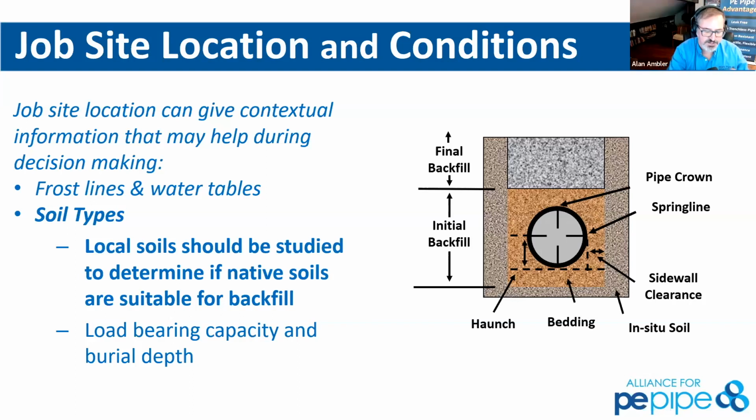That's a great question, and it brings us to one of the things that's plagued the HDD industry for smaller diameter quite a bit, which is called a cross bore. So a lot of times you can bore through a gravity sewer pipeline or a storm sewer pipeline, and then put your new smaller conduit through that pipeline, at that same elevation level at which we're having that conflict. Unfortunately, there's not really a rule of thumb that I'm aware of, Pete. The underground world out there can be pretty fierce when they're trying to put pipe in a new location and avoid everybody else in different areas.